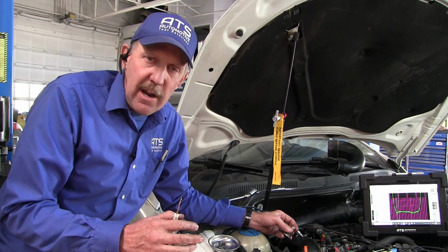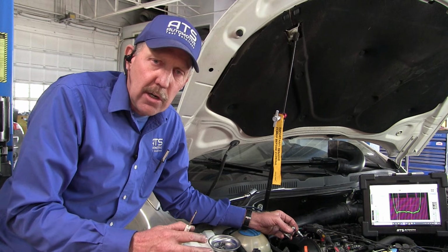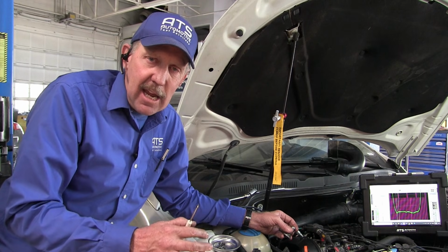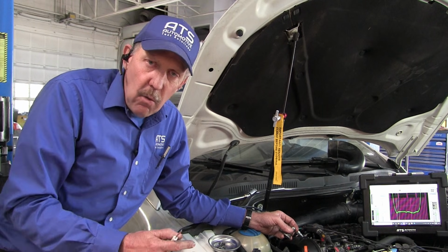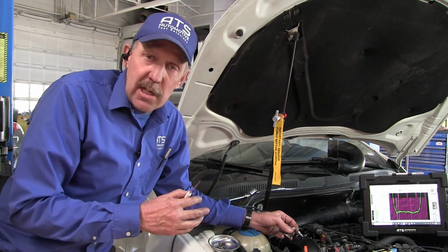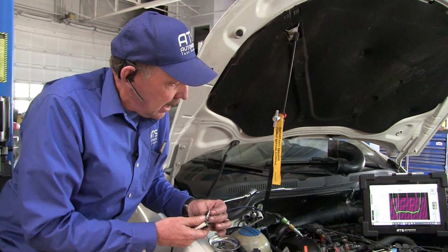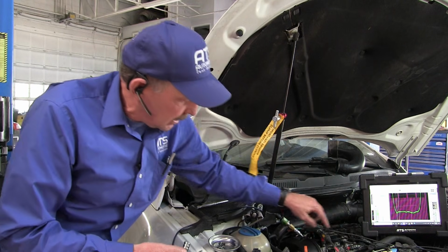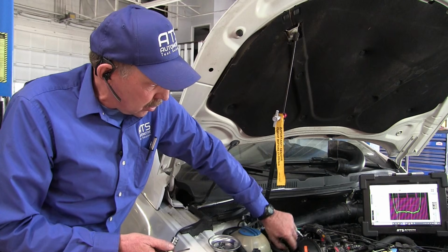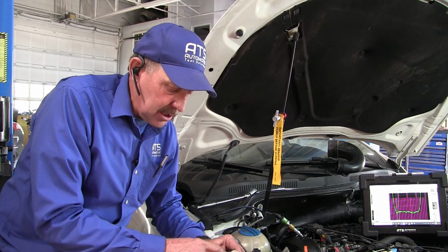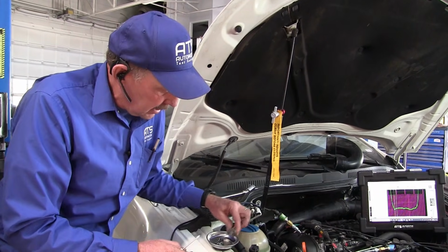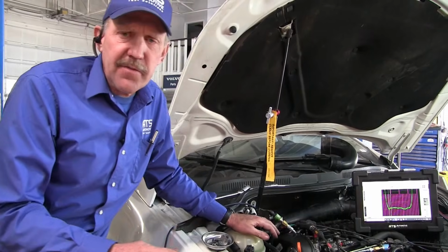The induction waveform was opening way too early, and we could see that the intake cam was out of time. That shows us that the exhaust was in time, the intake is out, and the intake is picked up by the sensor, and this is the control of the cam's movement. So then we have a good idea that this is broken. Once we get this in, the car's fixed.